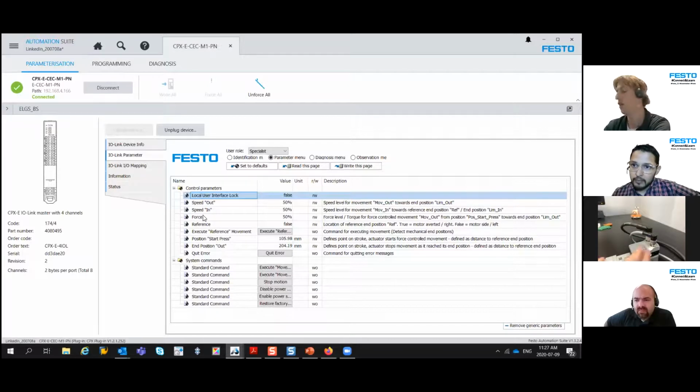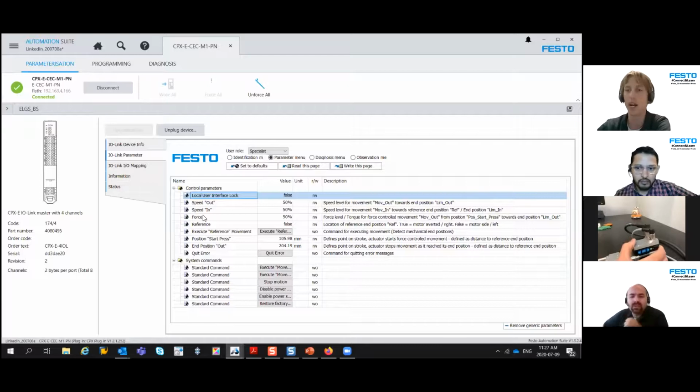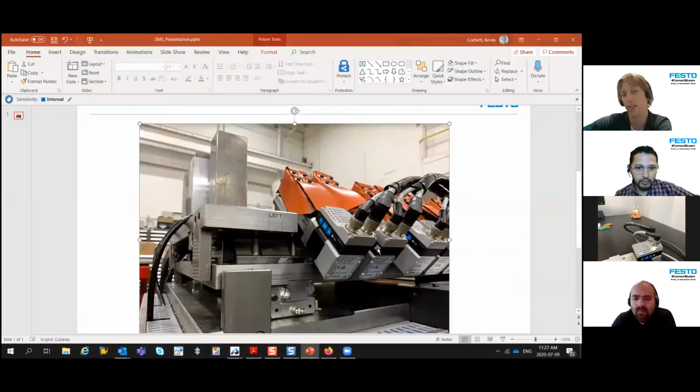Also, though, these buttons are an important point to touch on. You can use those buttons for setting all of these parameters. So if you don't want to come into the PLC and change these parameters through here, if you're more comfortable just doing the setup with the buttons, you can do it all from here. In my case, in the application that I worked on, we didn't have access to the buttons, so it was actually key for us to make those changes over IO Link.